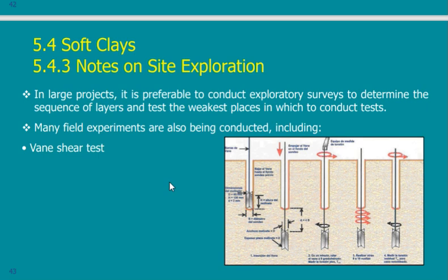So usually if I get a geotechnical report with all the data based on the lab, I expect they have ignored the soft soil because they did not get samples. To judge a geotechnical report in a place where I expect very soft soil, I should check the presence of field tests. In case I do not find any field tests, then I will say stop, this report is inadequate because they did not perform